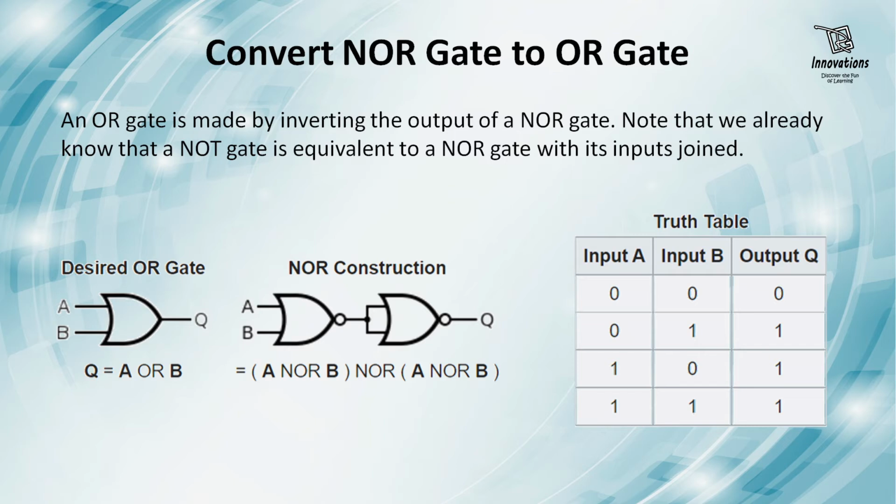We will implement this also using the 7402 IC. Since the 7402 is a quad 2-input NOR gate, there are 4 NOR gates inside that IC, so we can easily cascade 2 NOR gates in that. And now let us have a look at the circuit.